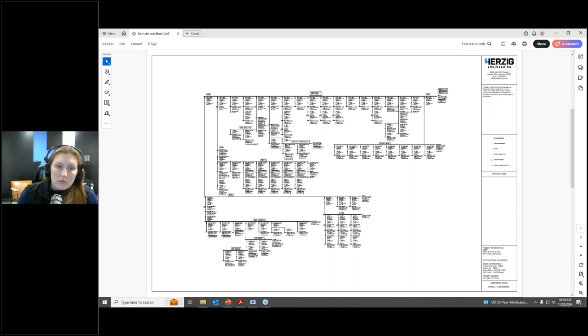for instantaneous, long time delay, short time delay, all that stuff. Fuses, their models, their sizes, relays, same idea. All that information can be listed out in what we call the protective device settings report.